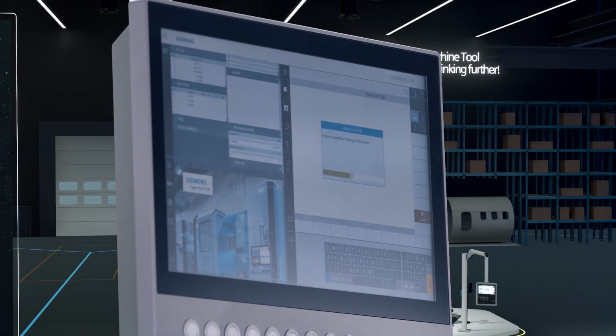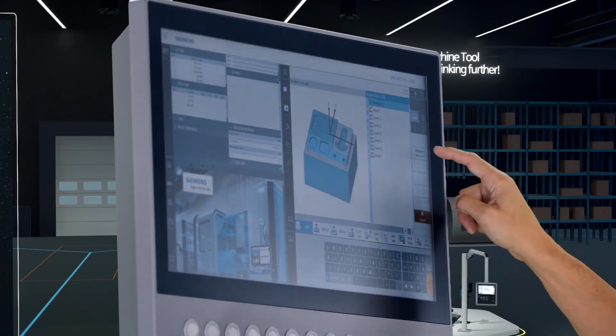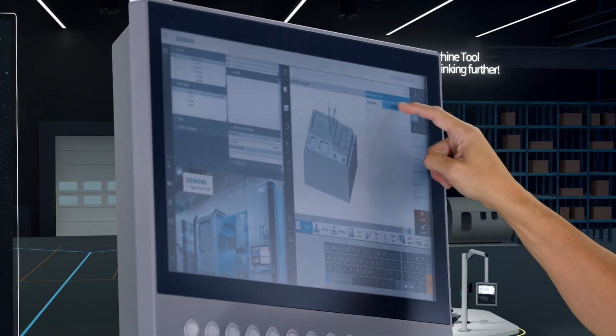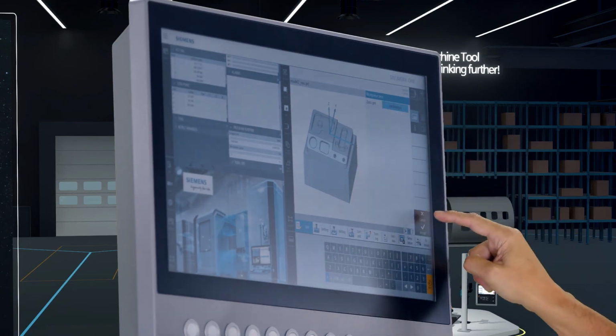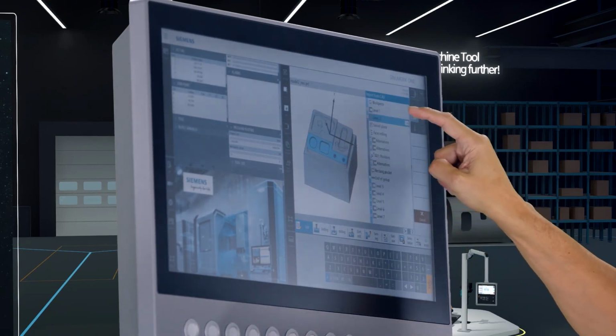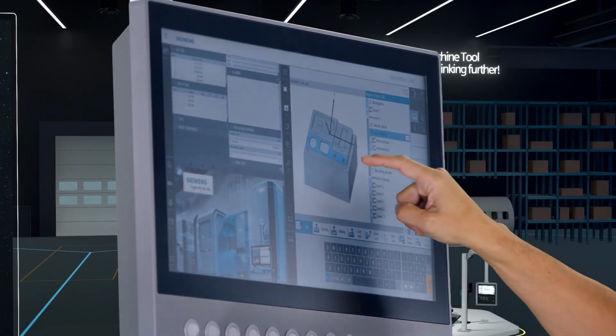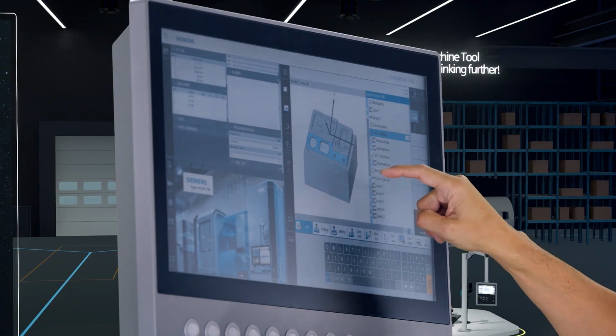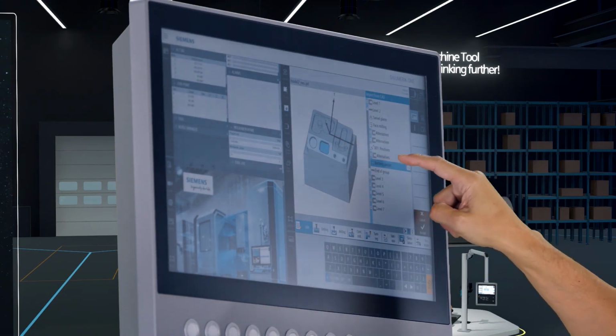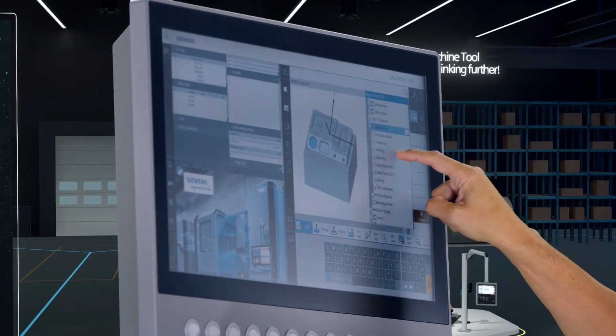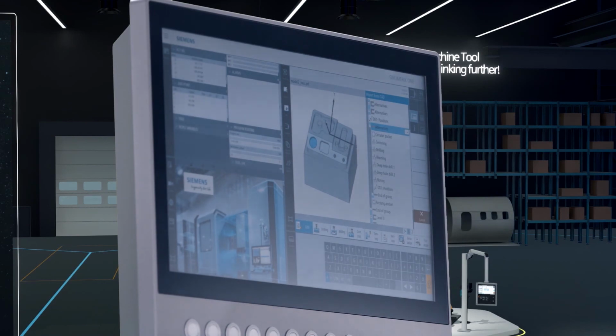With this feature, we are able to program at least as fast as on the CAD/CAM system. If you want to define a new workpiece 0 on a different plane or program on a different level, like when using our swivel cycle or swivel plane cycle 800, or using some rectangular pockets or some free contours, everything is possible.